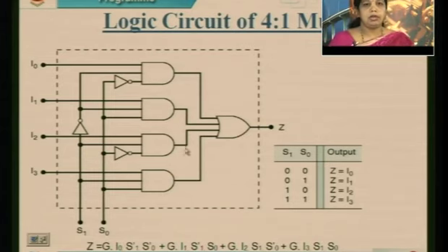What I explained previously was a block diagram. Now I am going to explain the internal architecture, or internal circuit, of the 4:1 mux. Till now you were watching only the block diagram, with 4 inputs, 1 output, 2 selection lines. What is inside this block? Inside this block there are gates, designed based on this equation.